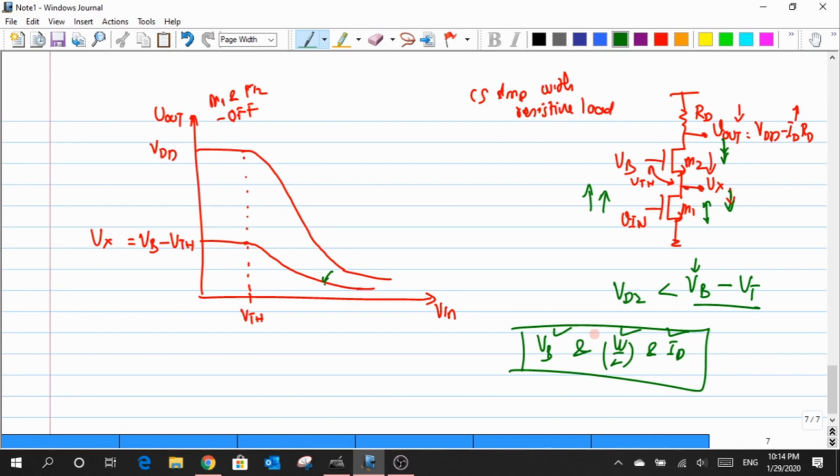Now, in order to boil down all these concepts that I have discussed, we have to work out an example to justify the statement that I have made right now. Obviously we know that both devices would enter into the linear region for a particular value of Vin which is more than that. Let me define this as Vin1. We don't know which one is entering the linear region first and which one afterwards, but let us assume that for a particular value of Vin, one among these devices enters the linear region.